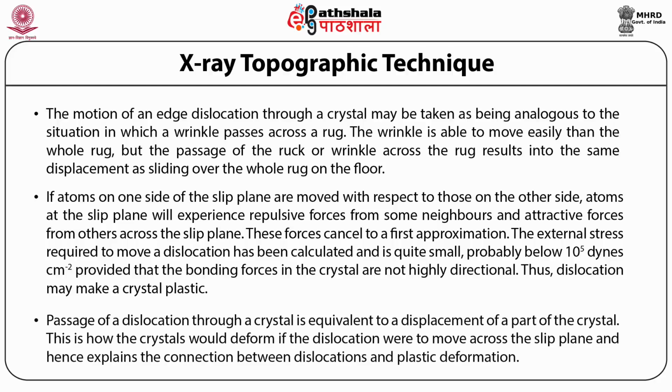Passage of a dislocation through a crystal is equivalent to a displacement of a part of the crystal. This is how the crystals would deform if the dislocation were to move across the slip plane, and hence it explains the connection between dislocations and plastic deformation.